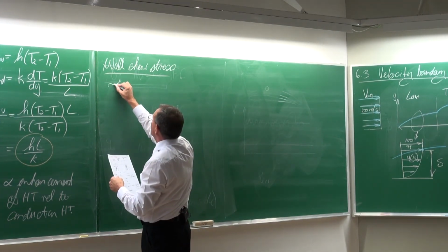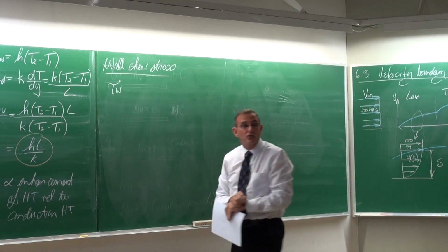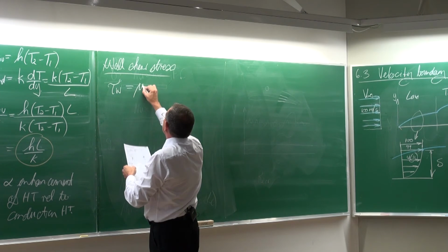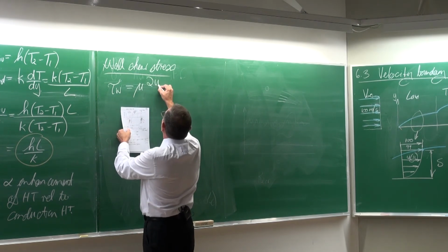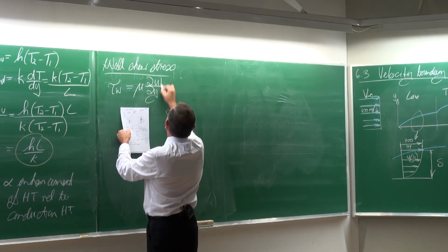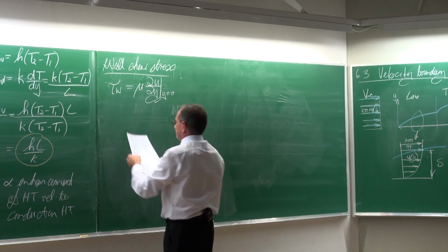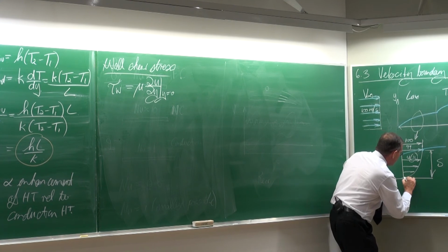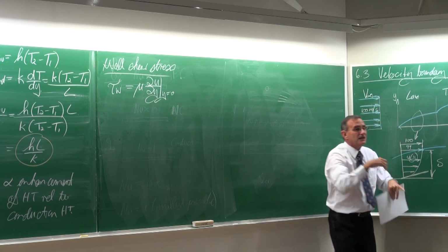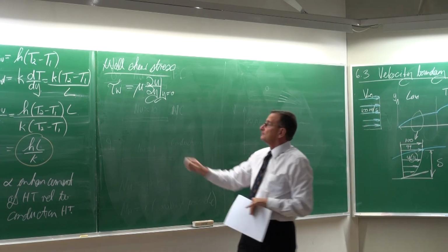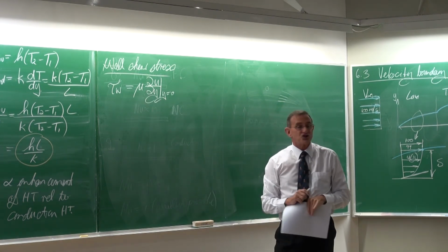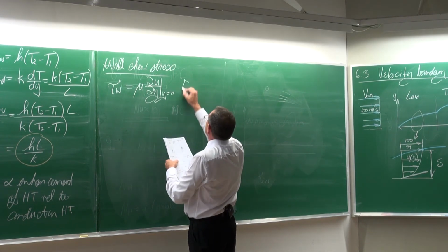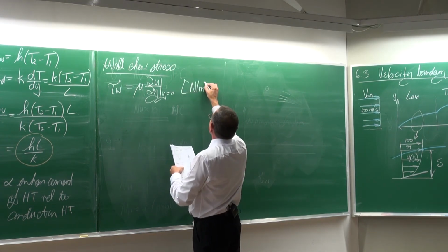So therefore just want to revise it. The wall shear stress is tau, and that is equal to the viscosity multiplied by du dy, where y is equal to 0. So where y is equal to 0, it means that gradient of the velocity boundary layer multiplied by the viscosity. And the units of it would be newtons per square meter.